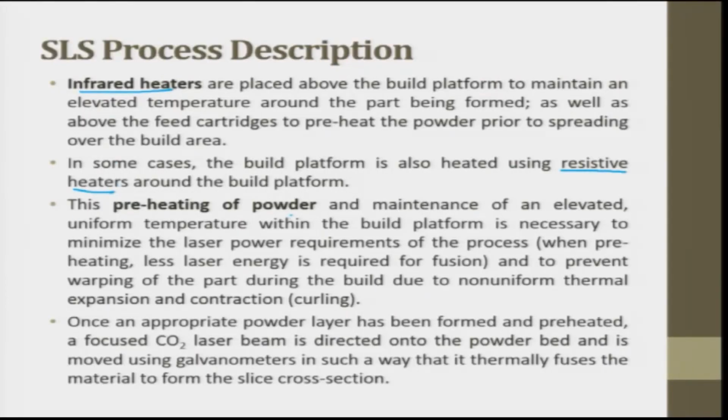This preheating of powder and maintaining an elevated uniform temperature within the build volume is necessary to minimize the laser power requirements for the process. Very important point. That is why we preheat the powder: to minimize the laser power requirements and to prevent warping of the part during building due to non-uniform thermal expansion and contraction.